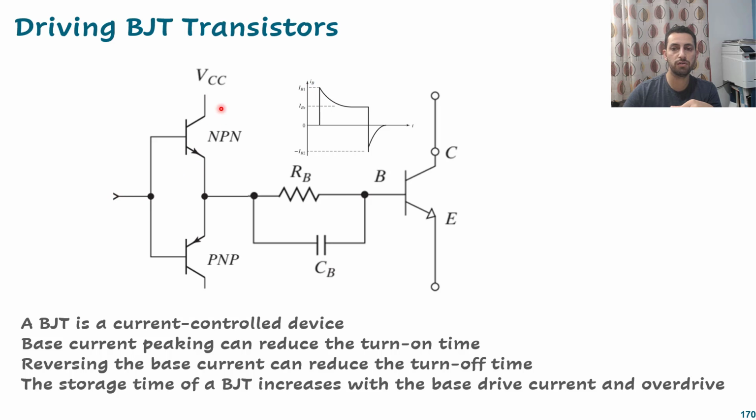And when we turn off that transistor, it will turn on that transistor, which is a PNP transistor. Negative voltage here makes the current go out from the base through that capacitor first, and then go there to the negative voltage here, or 0 voltage. It's better to be negative, okay? And that will deplete all the charges very quickly and turn it off.